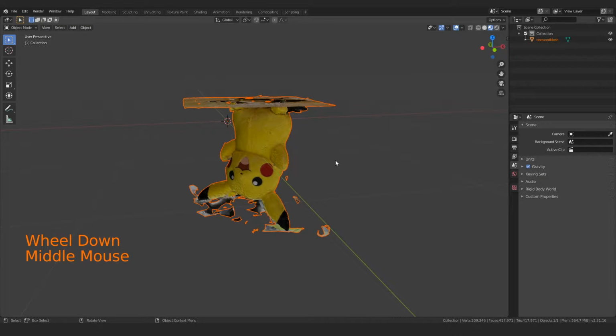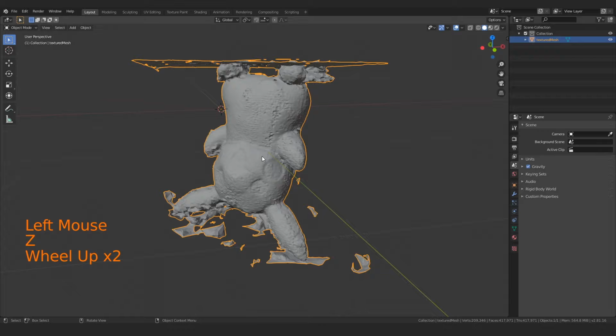So if I didn't have those PNG textures inside the folder, what would happen is this would either look exactly like this as a solid, or perhaps it would be pure white instead of gray, or even worse, this might show up as a bright pink or purple, a neon pinkish purple color, which is basically Blender's way of telling you, hey, there's supposed to be an image associated with this material, but it's not here. And so in that case, you would have to do one of two things. You would either have to manually relink the textures inside of your material properties, which can be kind of tedious depending on the number of materials you have. I happen to know, if we take a look here, this is the properties panel.